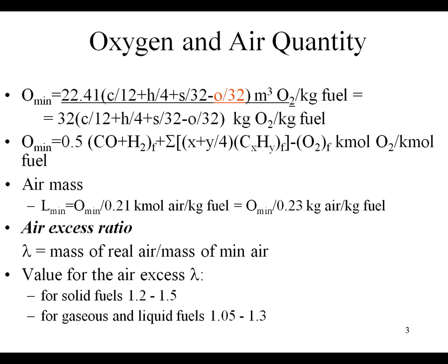Yes, unfortunately, not all the carbon finds the necessary oxygen, and that's why you have to stage it, to give more air in another stage of the combustion. But at lower temperature, when the molecular nitrogen is not able anymore to enter the reaction with oxygen, only the carbon can do it. The CO or the carbon can do it and turn to CO2. Is it clear with this air excess ratio values? So remember, you cannot make them very high, but normally they are about 1 and something, except in the gas turbines.